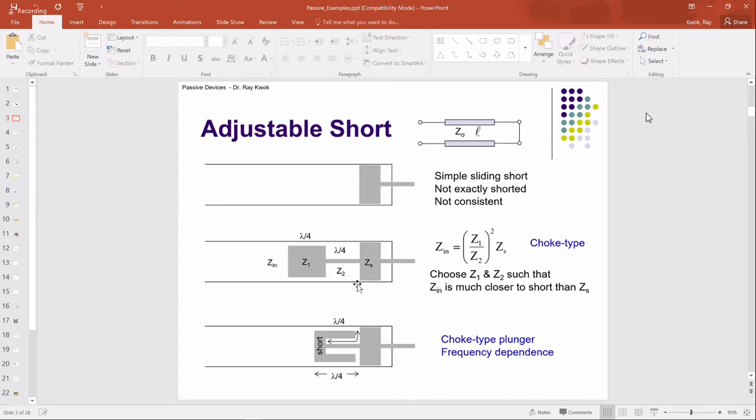The other examples, we talk about open stub and short stub. So when we have a short stub, for a printed circuit or coaxial cable, you can think of just joining the top active line to your ground, so to speak, right? But what about for a waveguide? What does it mean when we have a short? Well, we just have a short backing, just close it off with metal.